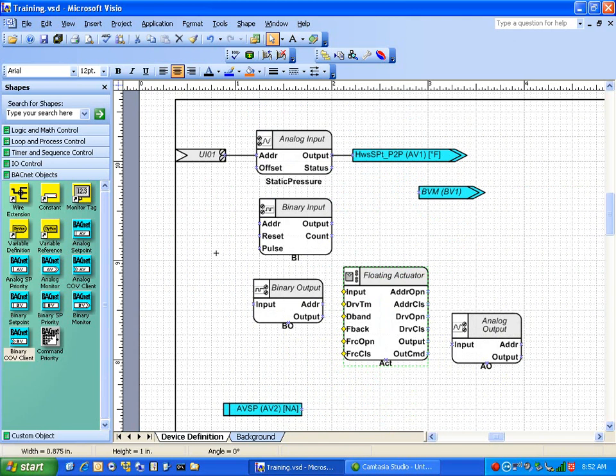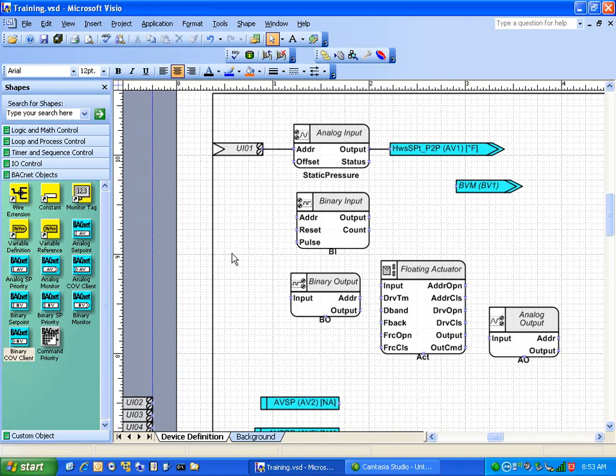And the BACnet I felt was pretty important. The COV is a big thing for the overall effect of your BACnet networks. One thing you do have to do: for every BACnet object up in the UNC, the COV does not work by default. Every BACnet object you'll see up in the UNC will have in the Properties tab a Use COV, and it'll be set to false. And then you'll have a COV increment. And yes, you can set a COV increment up in the UNCs.